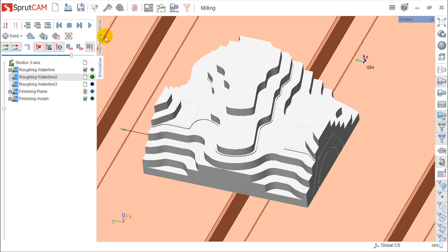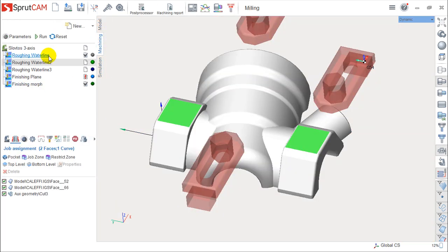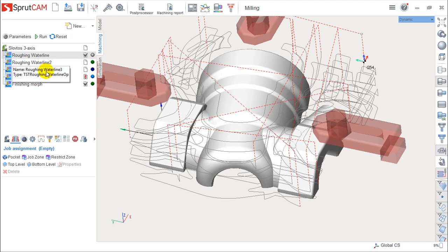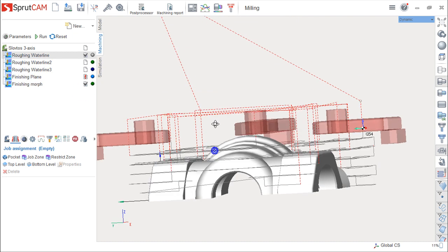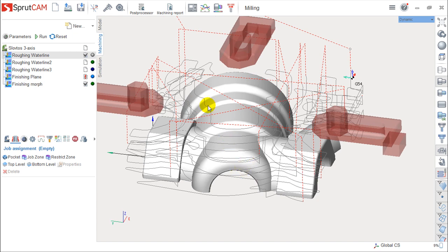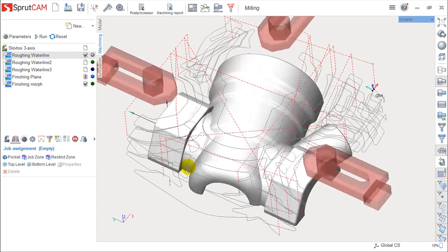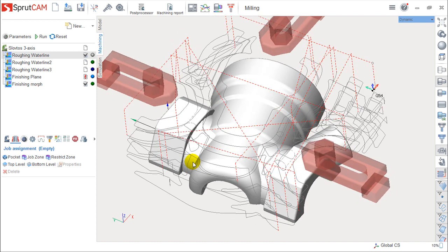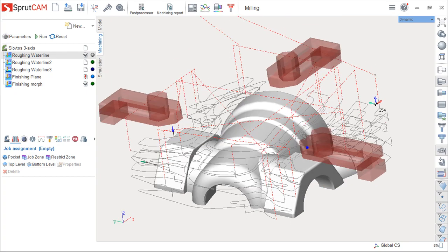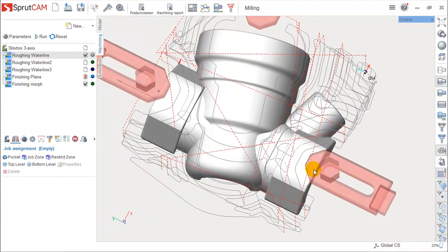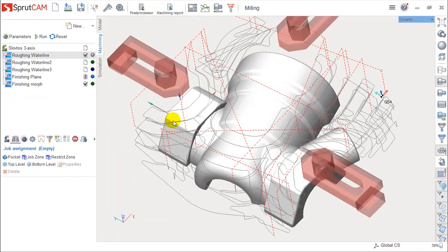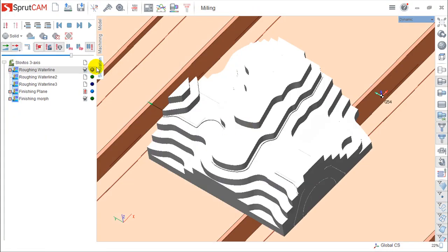Then we have other things. Let's go back. We have other parameters. One very important is something called machining step. And this machining step can have different formats, because it can be different from a toolpath that, like this waterline, creates these vertical layers, or a finishing toolpath which moves in a different way. So even on this waterline toolpath, we can try to simulate it.